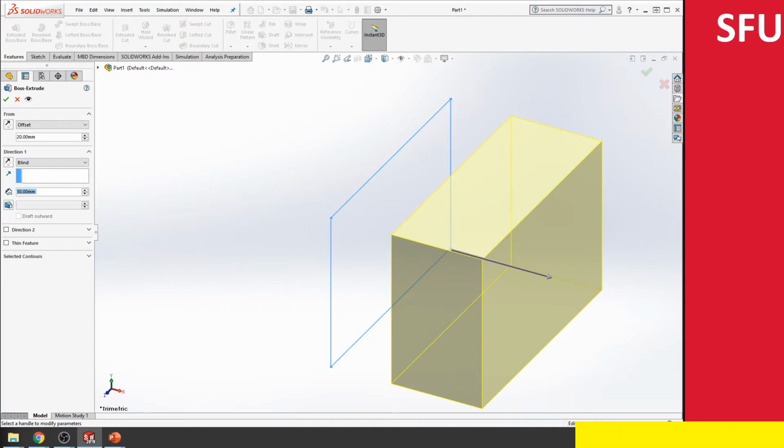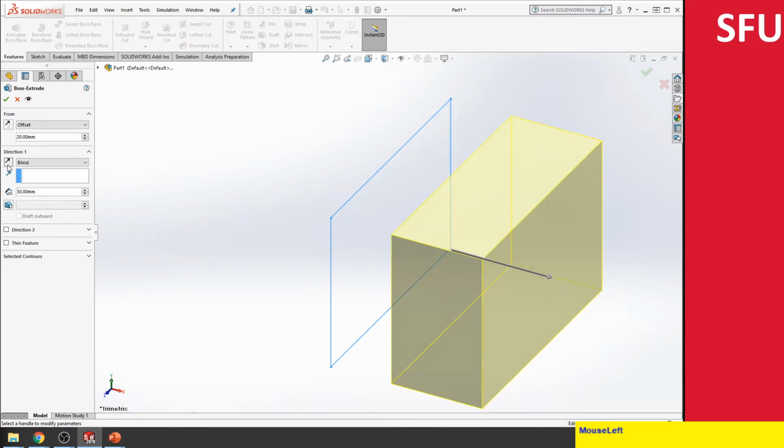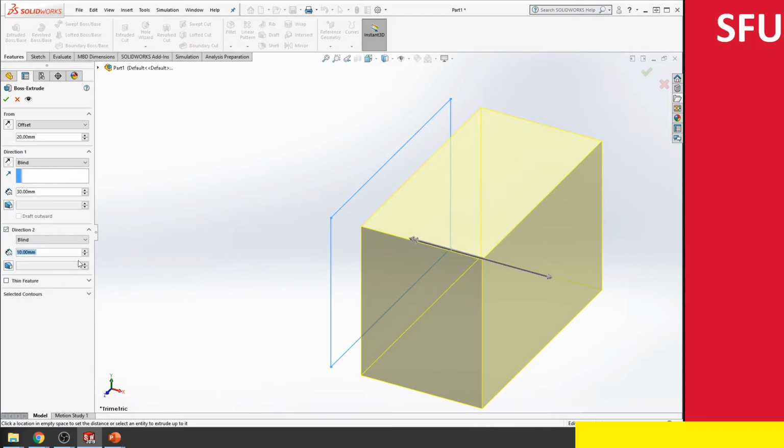So this has gone in this direction. If you wanted to flip the direction, you can flip and have the extrusion go the other way. Once we have the first direction, we can enable the extrusion in the opposite direction as well. In this case, again, it's blind by 10 millimeters. What we're going to do here is give a draft.